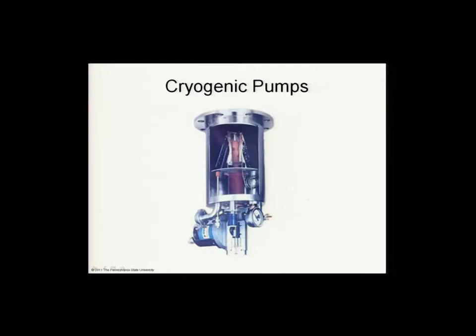Here's a depiction of a cryopump. And you can see the pumping's actually going on in here. Again, this is a capture pump. And so you capture. Obviously, you have to release what you capture. So when you're done pumping, you could close a valve up here, and then you could allow this to warm up. The molecules come off the surface, and you can pump them out. That's called regeneration. So these are generally not systems where you constantly pump on them. You generally use them, close them off, bring the temperature up, then pump off what's been captured, and that's called regeneration.